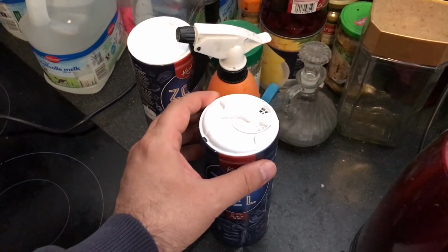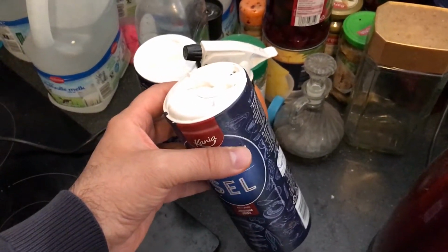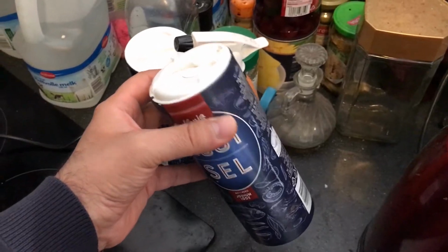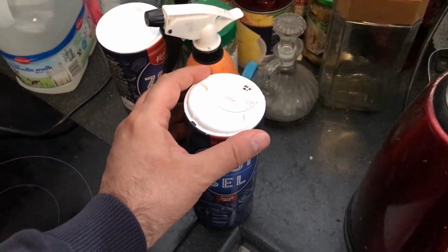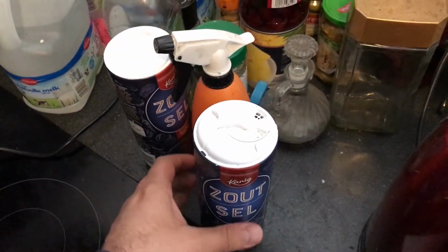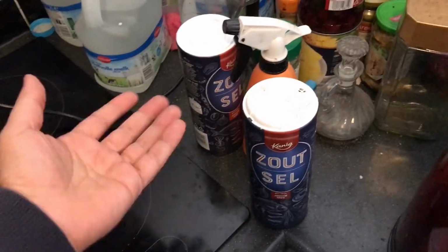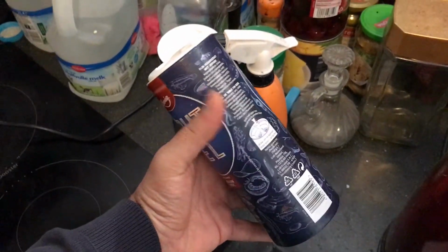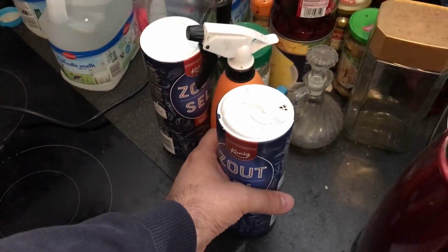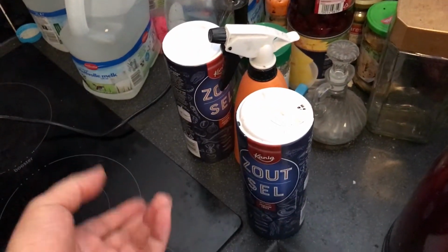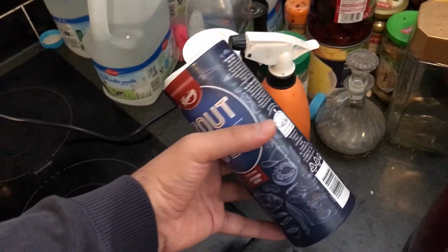So this material is made of cardboard. Paper and cardboard can easily absorb moisture. So if you leave this one in an area where the moisture content of air is high, or by accident you pour some water on it, it absorbs moisture, and if a high voltage is created over this coil, a discharge can form through this cardboard and basically destroy your secondary coil. So in general, it is recommended to use a better material, for example plastic, as this support structure. Maybe a PVC pipe is a choice. Also you have to be careful that the material that you use doesn't have conductive particles. So for example, white PVC or maybe gray PVC are good choices.